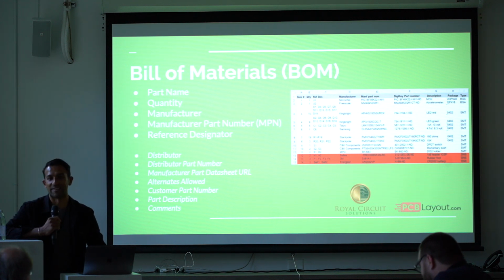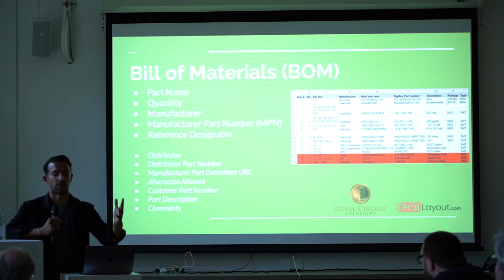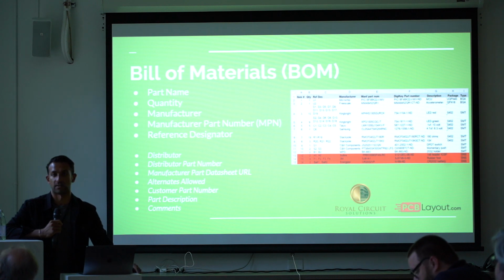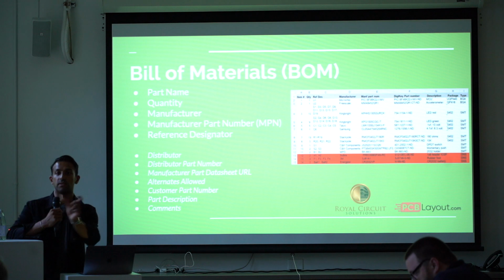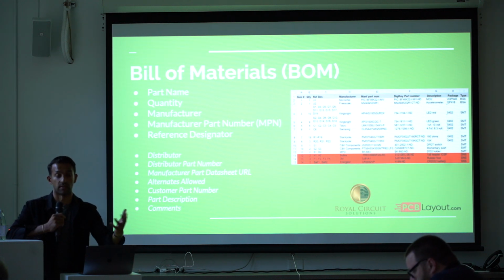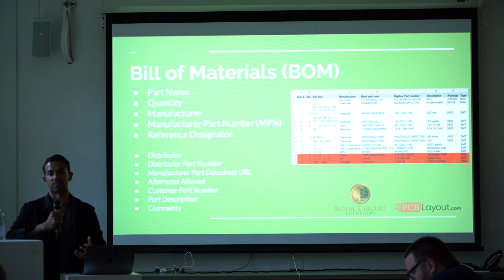Part name is not required, but sometimes it's just good to have for total clarity. MPN is good, but sometimes if there's a problem with the MPN, it doesn't link up with the part name. I guess the part name would be description. That's the most accurate way to describe it. MPN is fine, and what's the description? It shows up on DigiKey just so you can make sure it matches up, like this is an IC, it's not a diode or a resistor. Just a second sanity check. Although I can see how that adds a second layer of complexity as well.